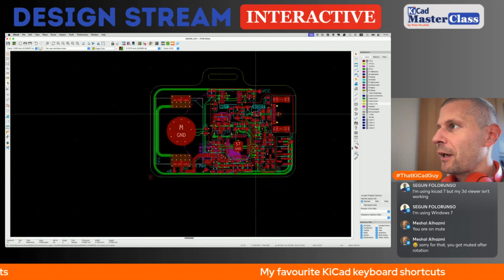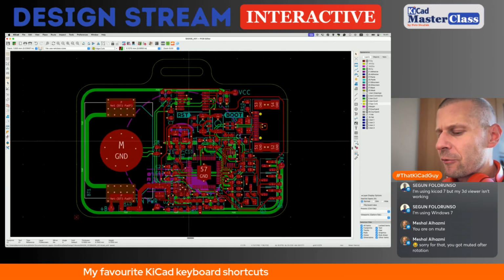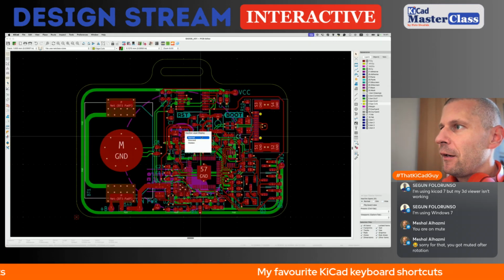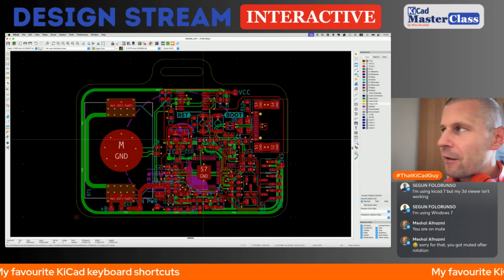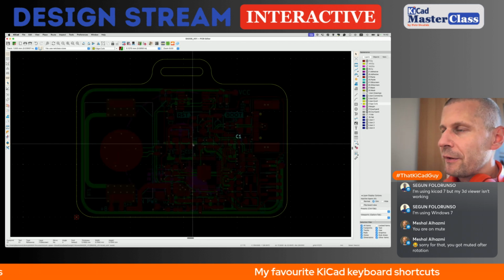I'm thinking what next. Pretty frequently, I'm using the H shortcut, which is the inactive layer display. This is the normal. You can see every layer which is enabled. When I press once, it's dimmed.